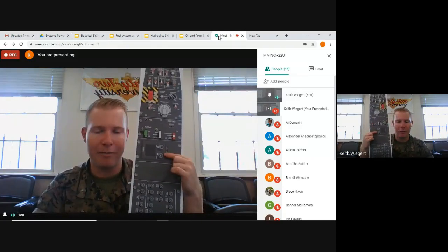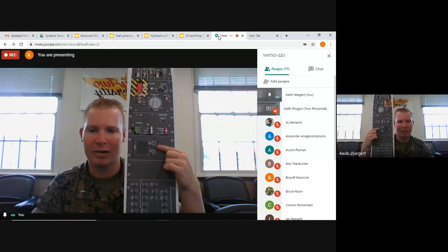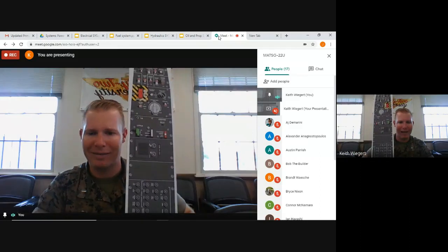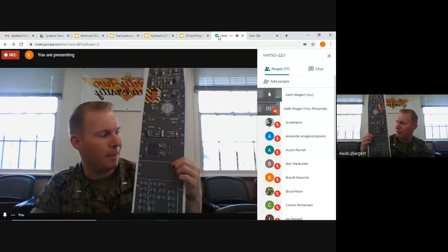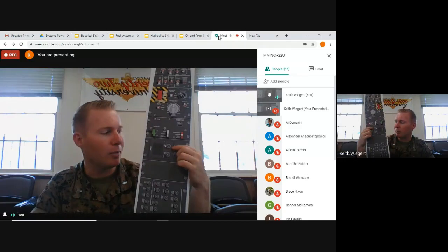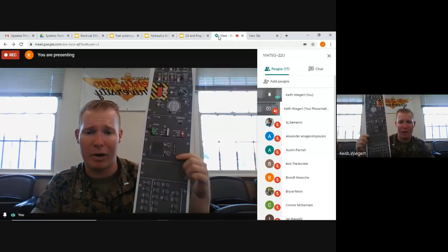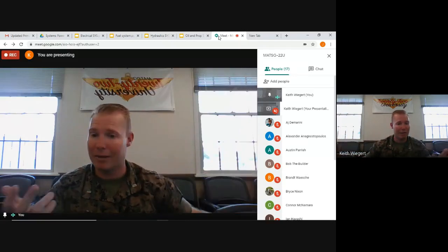It just gives us a different way to control how we use it, right? So that's going to be this over here. It's going to be on the right side, kind of like right here as you're flying the plane. That allows you to turn it on. You can dial in your frequencies. You've got your coarse and your fine tune. You can put both of those in there once you power it on. That's going to be using the aux-bat to power your VHF radio in the event that you lose everything else,